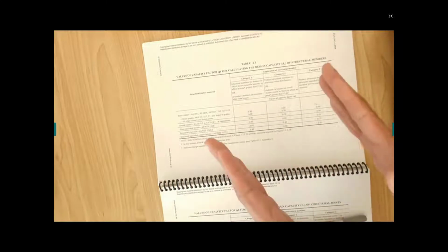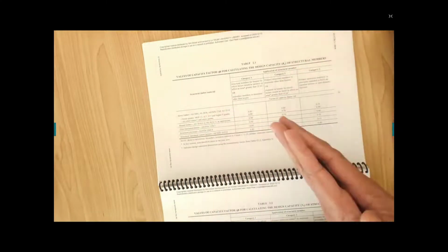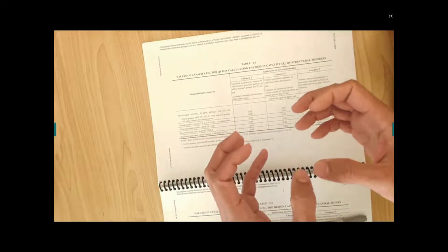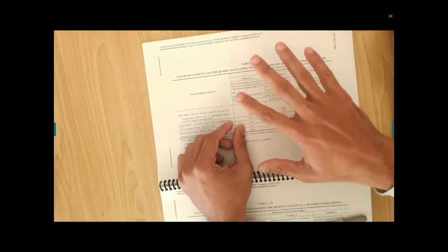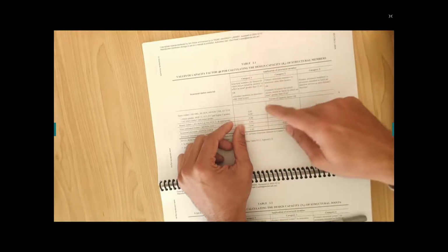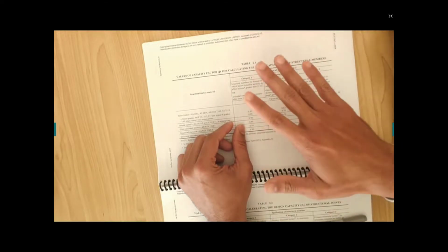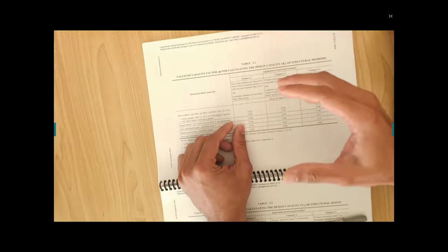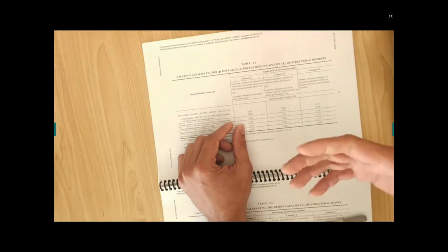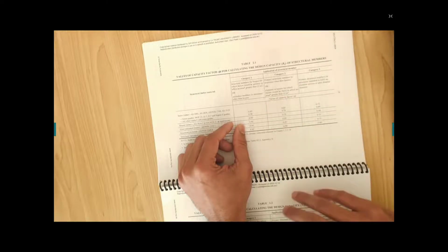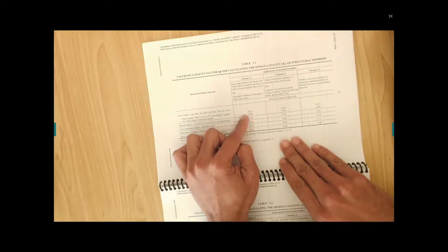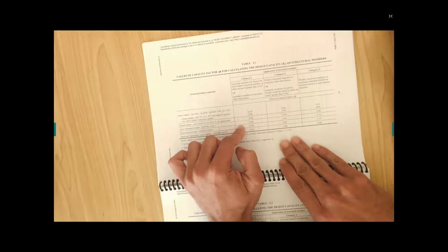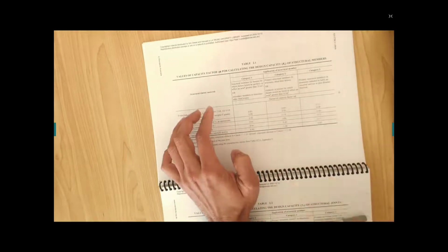By the way, this is a penalty. This penalty is applied considering the safety of the users: if something goes wrong, how many people will be harmed, or what will happen to the people living there. Category 1 is low consequence, meaning if it breaks, it will not have a significant effect, because it affects only a small portion of your house. Probably someone is not on that portion most of the time, so only a 5% to 10% penalty is applied. It's just a reduction of your bending capacity.